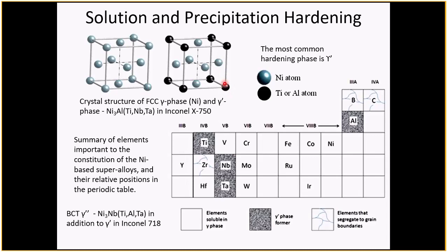It's this direction on a 111 plane, which is the close packed plane, which I don't have identified here. It's along here and up here. This is kind of this triangle here. So the 110 slip on that plane, if you like, you displace on this plane, I wish I'd drawn it now.